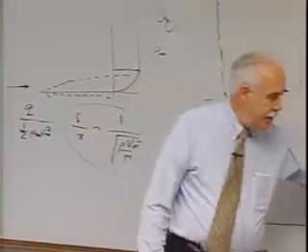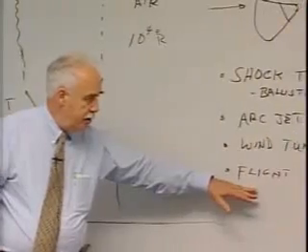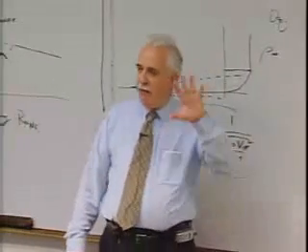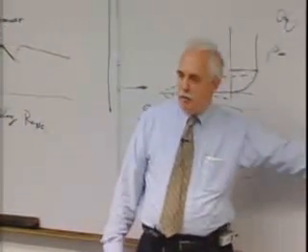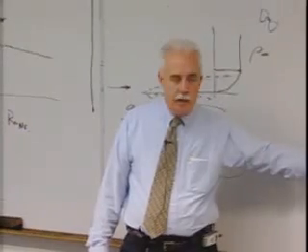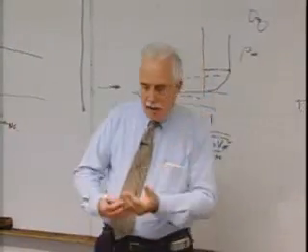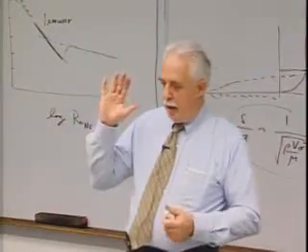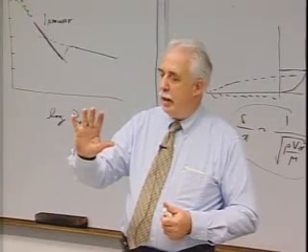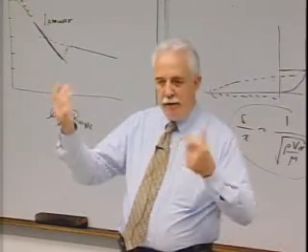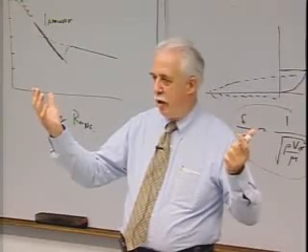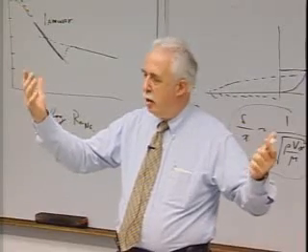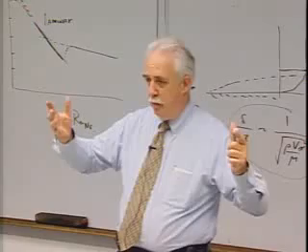NASA Langley built a small-scale Apollo, about so big, to measure the radiation in flight, because the shock tubes were operating at slightly higher pressures than we were going to fly the Apollo. It basically had three beryllium heat shields with a quartz window in it. It comes in at zero angle of attack, and gets to a given point where the window basically starts to melt. You can't see through it, you can't make a measurement. It sheds that. And ideally the second heat shield comes about right at peak heating, simulating the Apollo entry, and then